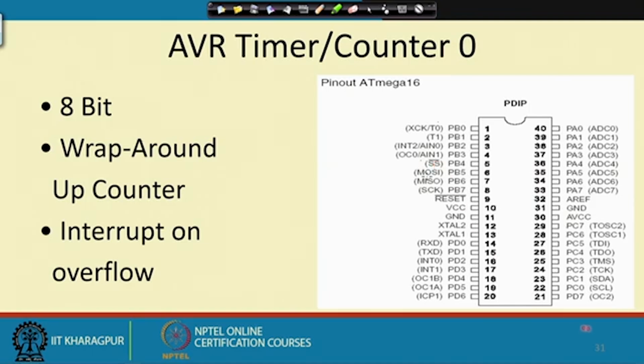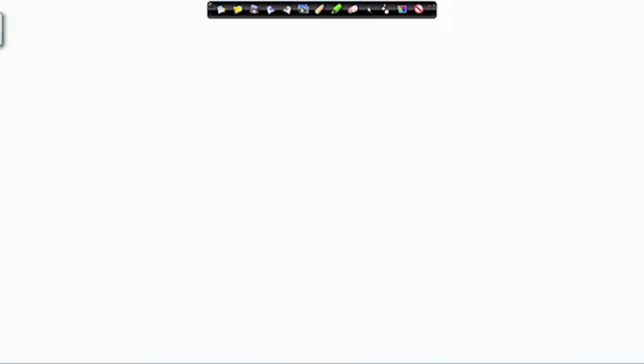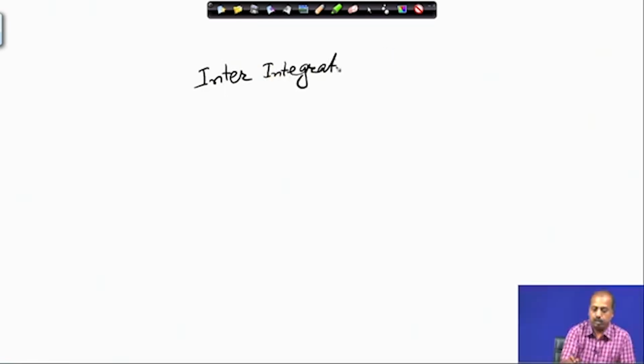Another interesting interface here is via the SDA and SCL lines. These are for another type of interface known as the I square C interface, for inter-integrated circuit. It has various names: IIC, I square C or I2C.